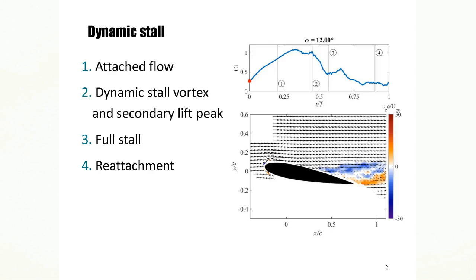Here is the result of the dynamic stall development for one of the cases. This case has a reduced pitching frequency of 0.1. On the top is the lift coefficient from the pressure measurements, and at the bottom is the flow field from the PIV measurements.